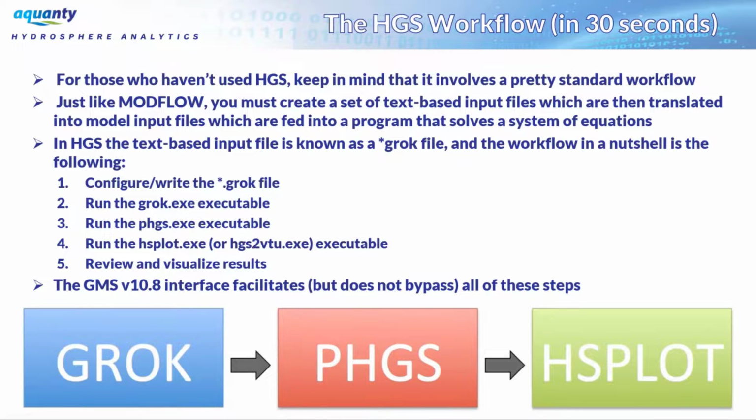Basically, just like MODFLOW, you do need to create a set of text-based input files, which are then translated into model input files, which are then fed into a program that solves a system of equations. In the world of MODFLOW, it would be one of the many different MODFLOW engines, whether it's MODFLOW-NWT or MODFLOW-2005 or MODFLOW 6. In HydroGeoSphere, the program that solves the system of equations is known as phgs.exe.